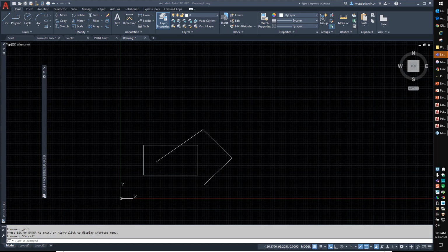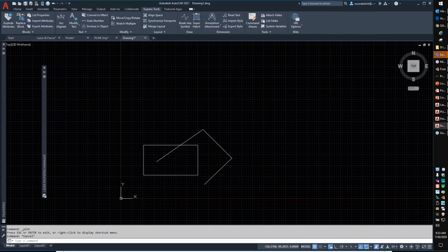All right, is there a way to make the entire drawing coplanar, i.e. some items are drawn at different elevations and properties and I can't set Z to 0? Okay, so there's a couple of ways to do that. If you are using full AutoCAD, you have an Express tool up here called Flatten. There should be Flatten Objects. This is usually the first thing that I would try. You select everything. What it will do is flatten everything down to an elevation of Z equals 0 wherever possible. There are situations where it cannot.